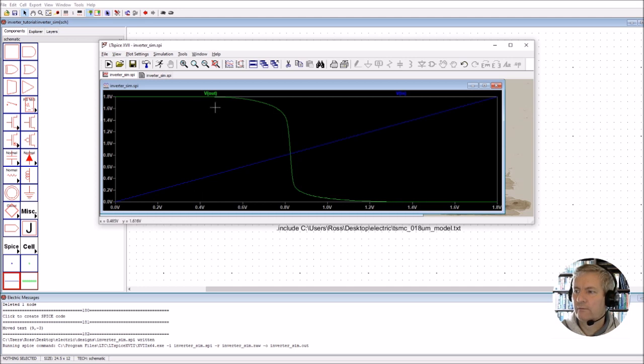Now in this instance we've got 1.8 volts for the supply rail, as opposed to the 5 volts we had been talking about previously. In this process we want to keep the power as low as possible, and you can do that by keeping the voltage level at the power rail as small as you possibly can. So that's why we've got it down at 1.8 volts. But that's just details for us at the moment. We just want to know how to run the tool, simulate it and get it working. So that's the DC analysis.